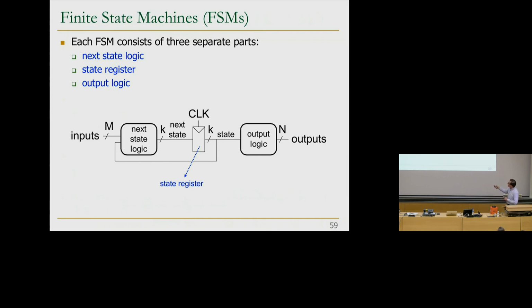So you need to encode them with a register. You need to remember this, basically. And that's encoded with 1s and 0s. And if you have 4 states, you need 2 bits to encode it, right? Basically, the state register for the light will be 2 bits. The state register for our sequential lock will be 2 bits also.